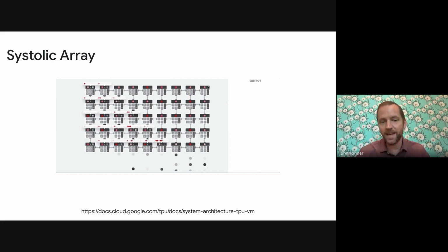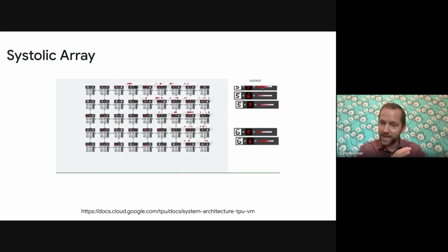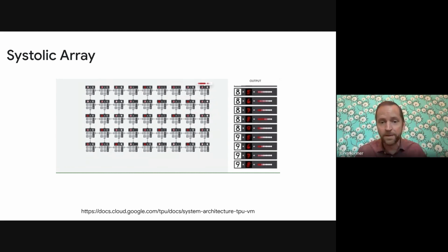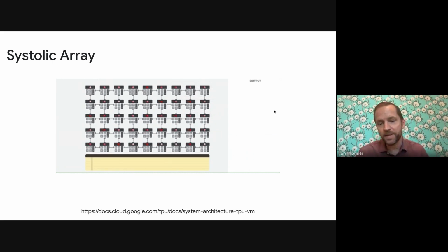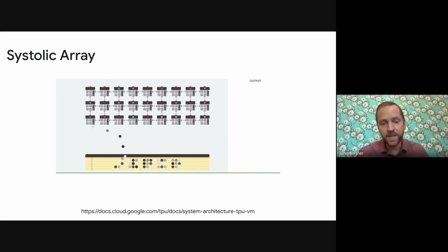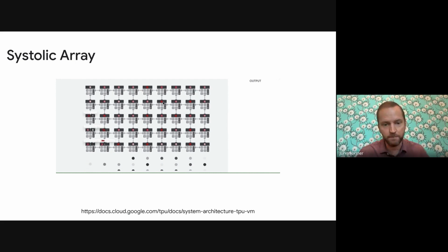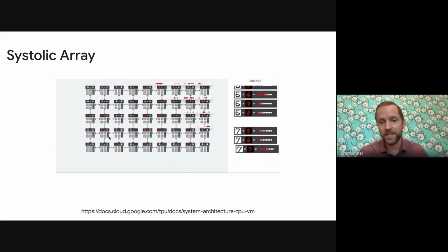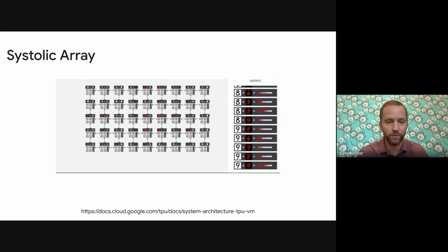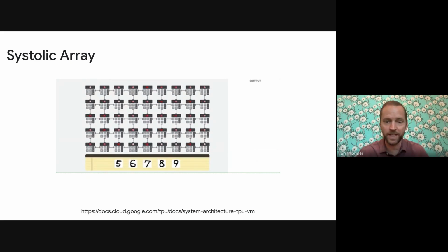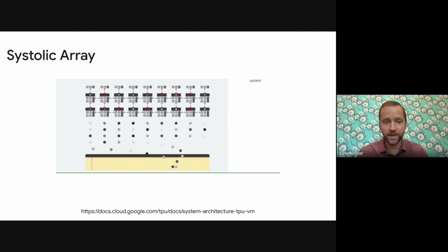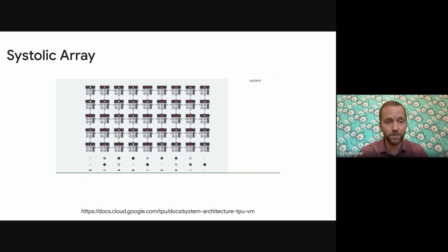So this systolic output also means that your output is kind of coming in pieces and overlapping. This overlapping makes it a little bit more complex. That complexity is handled in software, it's fine. But the thing that it really does well is it keeps the input buffered. It keeps these computing units completely fed so that you're not having any idle cycles, and the TPU can really shine and constantly be performing the computation that we need it to, and it's really nice. So this was a really big part of the system architecture, the TPU, and a big part of the innovation there.